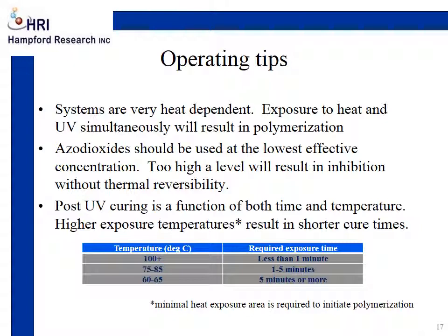You can see at over 100 degrees C, it required less than a minute to initiate curing, whereas at the lower temperatures, 60 to 65 degrees centigrade, it took 5 minutes or more for the system to cure. What's interesting is the entire area does not need to be exposed to the high heat, only a small amount of the epoxy. The exothermic characteristics of polymerization generate enough heat for it to become autocatalytic and continue to cure, giving very deep cure characteristics.